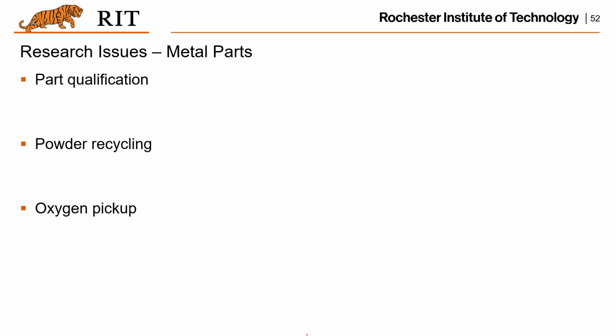Again, qualification will be a very big problem for many applications, especially when you talk about aerospace, airplane, and bio ones. You have to make sure the built part will be as good as the one built using other manufacturing processes. And how to recycle the powder, right? Because the powder is so expensive, definitely you want to find a way to make the best of recycling the powders. And yeah, that's pretty much all for the metal additive manufacturing.